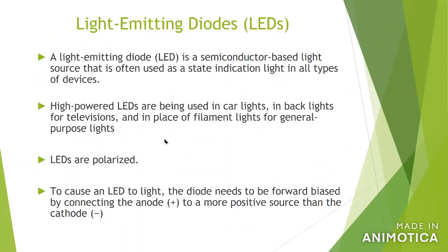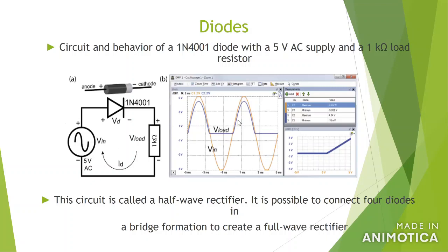If we go back to that specific slide, you can see if we only have a diode, then the output will look like this, the blue curve. The blue curve is the voltage for the output for this load, because for the negative voltage, the diode will block it.